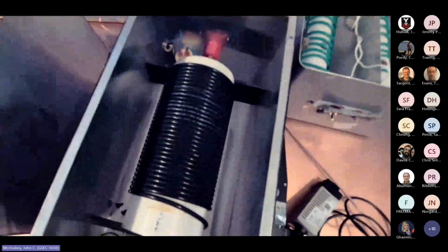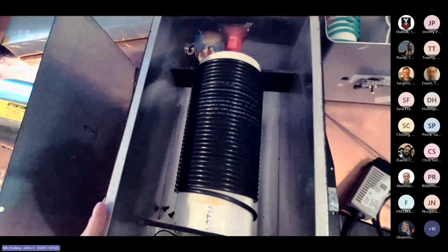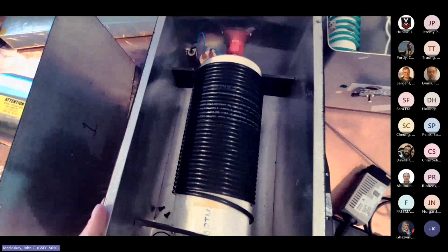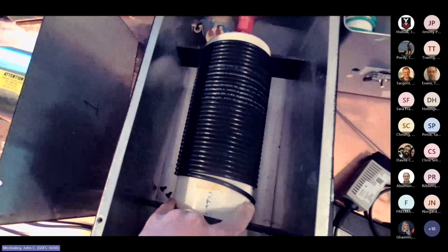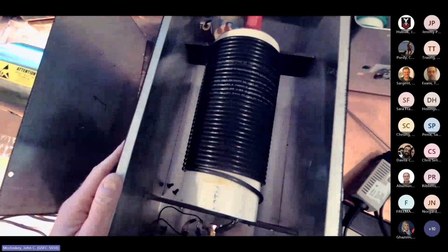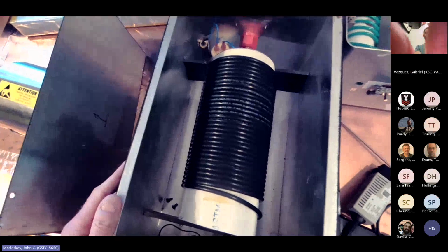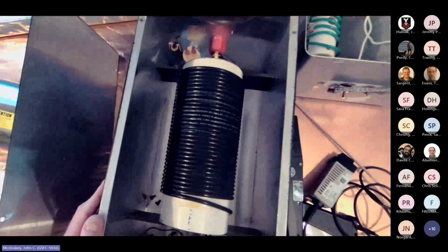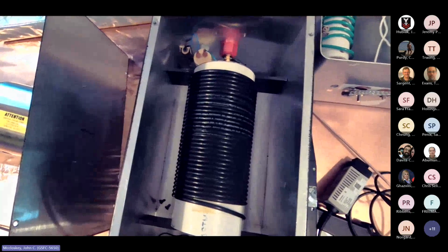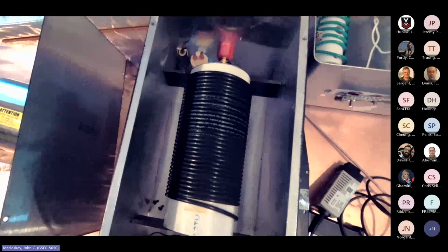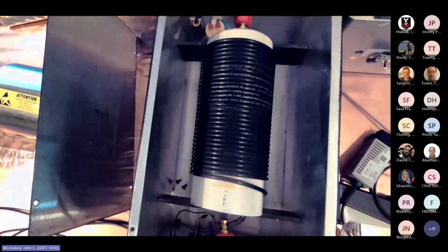Well, look at what's inside. That's a 50 microhenry inductor. I'll put my hand here so you get a sense of scale. I like to show this to emphasize that 50 microhenries is not something you get by accident. You have to mean it. That's a 4-inch diameter piece of PVC, and I haven't counted the turns here, but it's a couple dozen, maybe 3 dozen turns. That's what it takes to get 50 microhenries, which is representing a wire 5 centimeters above structure on an aircraft or a ship, on a military platform, with structure as the return current path.